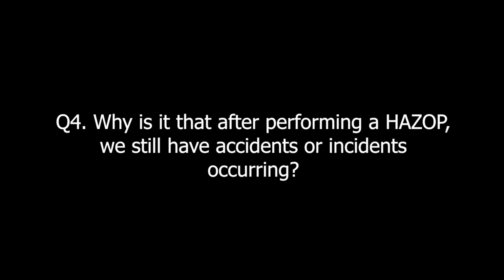If one of those shut-off valves gets compromised, even one of them during the operational phase of the plant, then your HAZOP doesn't count for anything. If that valve is not maintained properly, for example, or inspected to then check and change out when it's not working properly, and so on. Your pipe work, if it's not inspected, if there's no fire detection, gas detection or the fire detection is not working or is not spec'd properly.